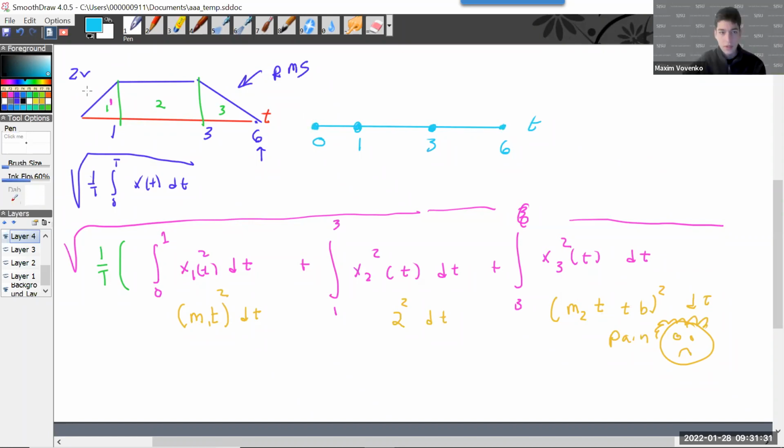Professor Parent, weren't the rise, fall, and on times 1, 2, and 3? In this case, it looks like you've written 1, 3, and 2, because the rise time is correct, but then the on time is 2 seconds in these calculations, and the fall time is 3 seconds. Wasn't it the other way around in LT Spice? The rise time was 1, the on time was 2, and the fall time was 3, right?